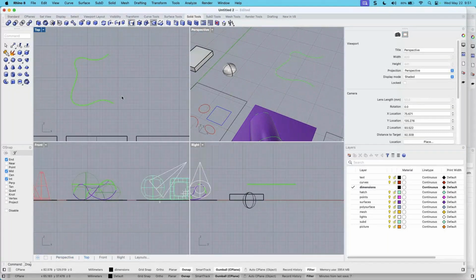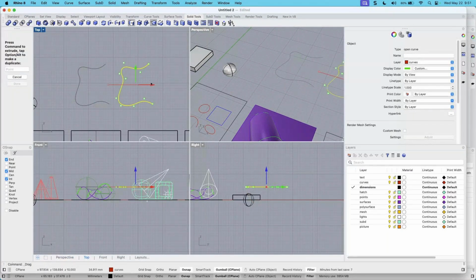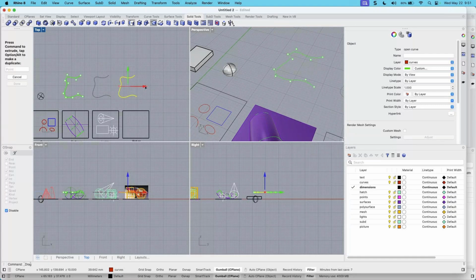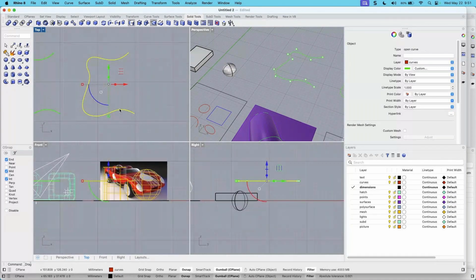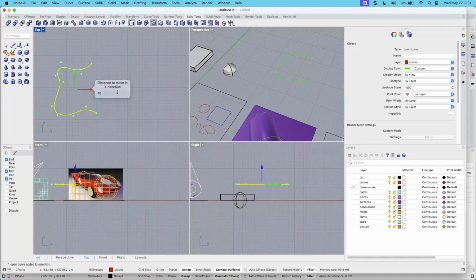And if you want to copy it, not at a specific distance, you can tap the Alt key and copy it. Okay. Now you might be saying, well, I want to copy it 10 units to the right, Mary. Okay, what I'm going to say to you is you're going to copy Command C, Command V, so you get two of these, and when you have two of them, then take one of them and use the move command.